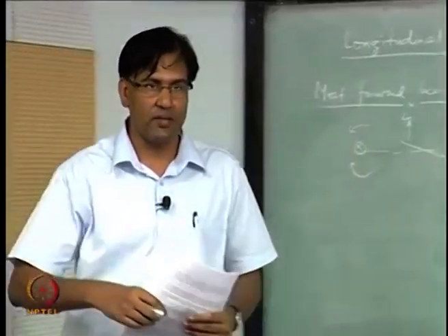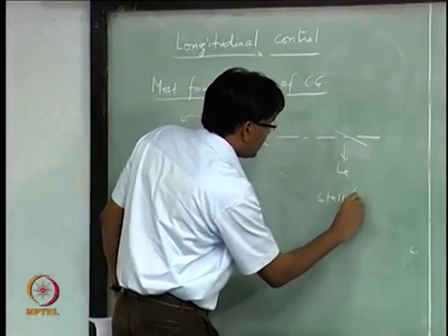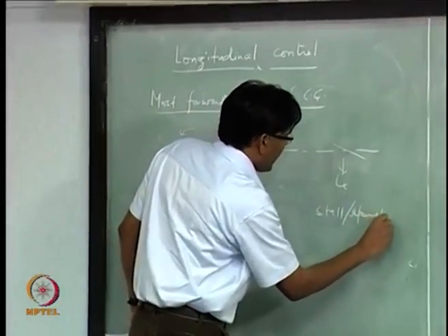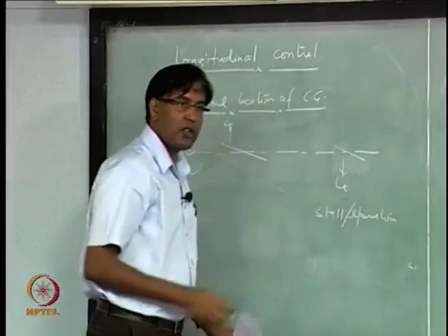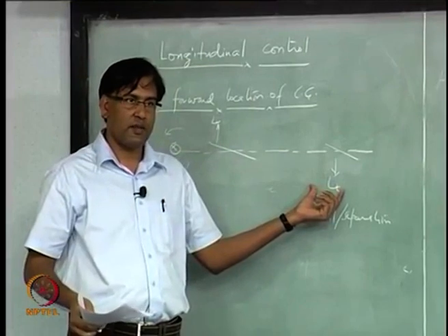Once you start going beyond that delta E max, there will be stall and separation of flow, and this LT will start decreasing, right.